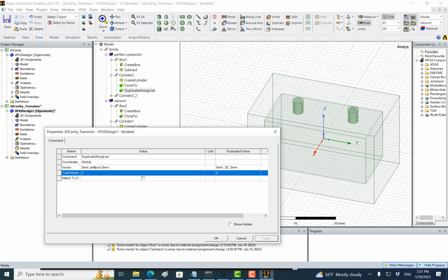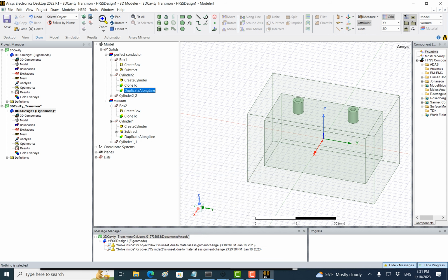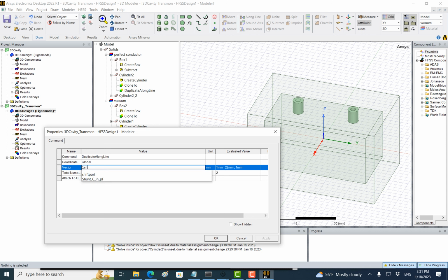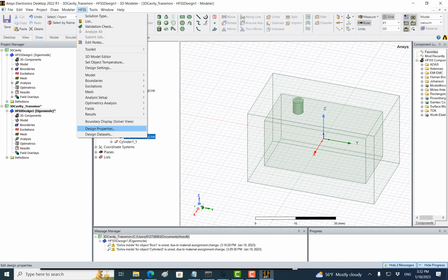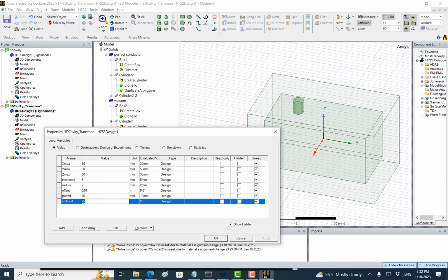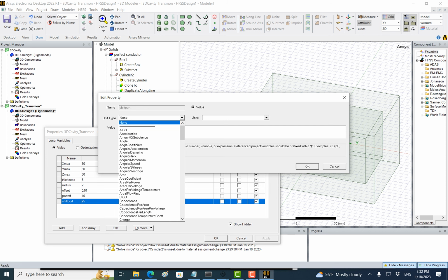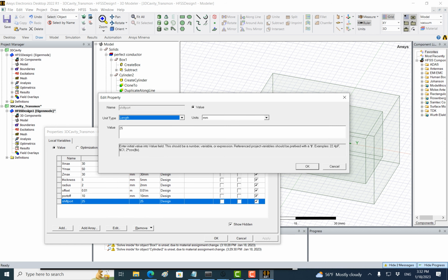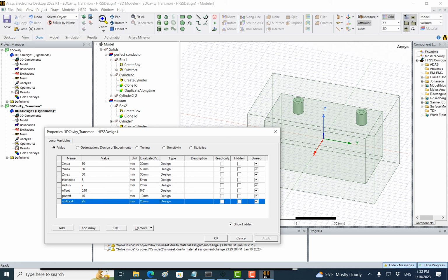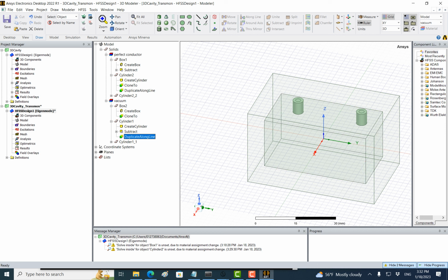And then when you apply, you get this, right? But you see that something is lost because we also need to shift this one accordingly. Okay, so this is 0, shift pot, right, by 0. Okay, apply. I forgot to give the correct units again. Okay. So let me go to here, see if I can fix it. Edit. Okay, actually I can load that. I can fix it. This is the length L, and the units is millimeter. Okay. And then if I apply, it will come back, right? So this one is shifted a little bit too much to the edge, but that's okay. We are just doing some testing, right?